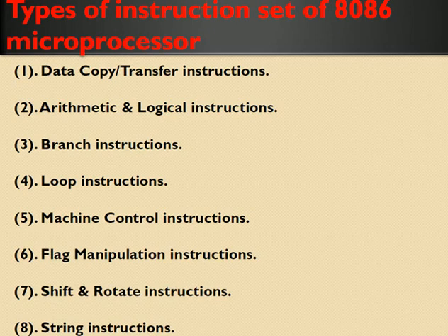Okay, you know very well 8086 microprocessor, it can support 8-bit also. Here, using an 8-bit instruction, MOV AL, 08 means move 08 data into AL register. Here AL is an 8-bit register, and AX is divided into two 8-bit registers, AL and AH. So the important data transfer is move the data from one to another, or move the data from source to destination instructions. Okay, and then next different types of data transfer are increment, decrement, etc.